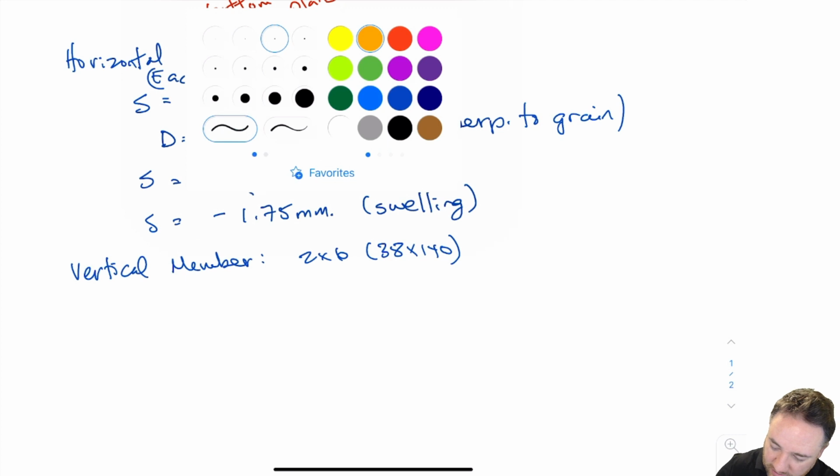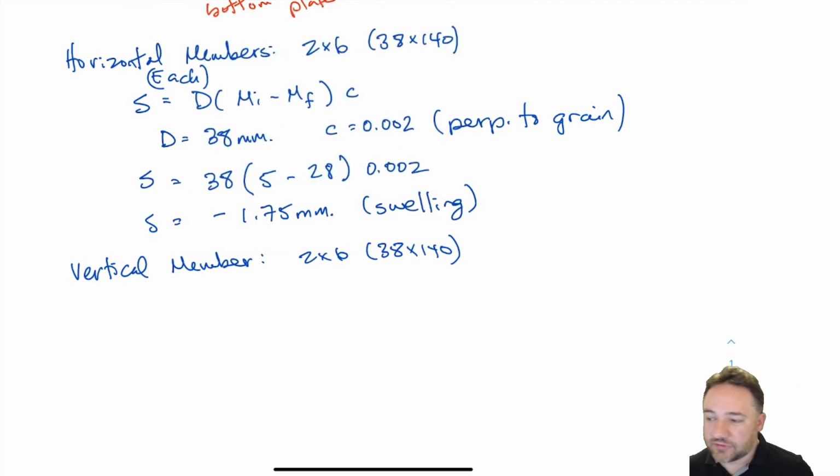So just to remind ourselves about how we convert feet to millimeters: we've got 12 inches in a foot, and each inch is 25.4 millimeters. That's something that you really have to put to memory because, especially in wood construction, we sometimes run into things that are in inches instead of in millimeters, and we need to know how to convert them. The only thing that you really need to remember is 25.4 millimeters per inch, and you're going to be just fine.